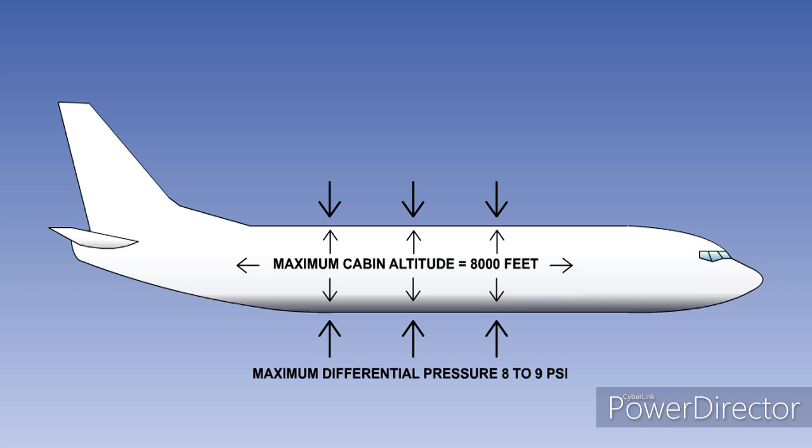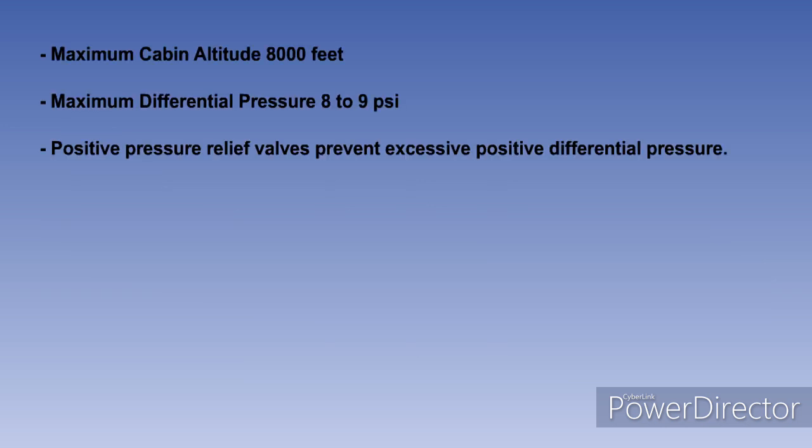You should also know that the pressurization is controlled by having a constant mass flow of air into the fuselage and controlling its exit using outflow valves. You should understand the purpose of the various safety devices fitted to a pressurization system. The positive outward opening pressure relief valves prevent the structurally limiting maximum differential pressure from being exceeded.